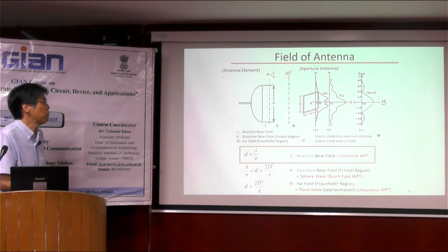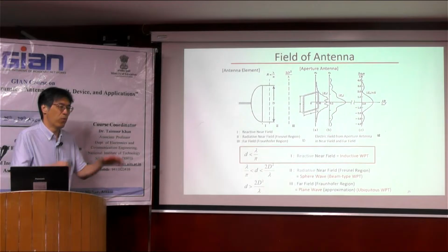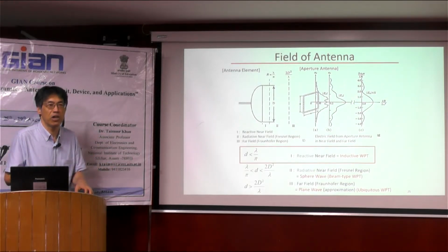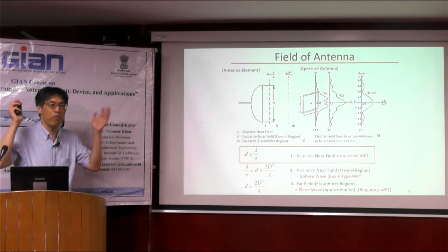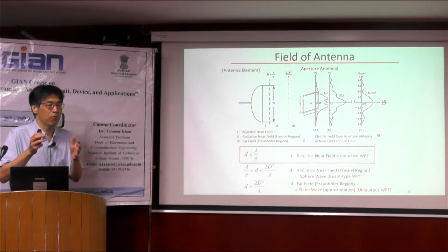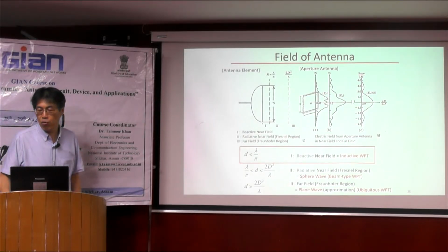the field of the antenna changes to the reactive near field area. It means both antennas will be coupled electromagnetically, like inductive WPT. So please remember, the Miyagi-Uda antenna uses a coupling phenomenon. So in this area, what happened?